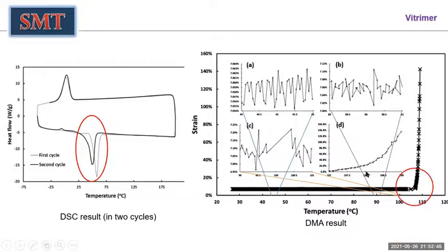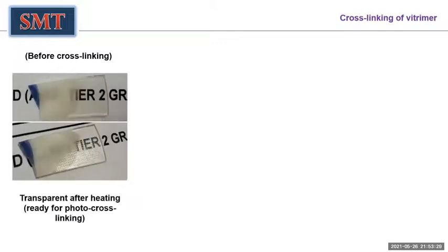The material only starts to flow over here, well over 100 degrees, at 107. Melting means it's easy to flow, but you need to heat to a much higher temperature to make it flow, because all the cross-links have been destroyed and the material becomes thermoplastic. And this is a very important feature. We can cross-link bitumen, and then we can use this feature for 3D printing in solid state.